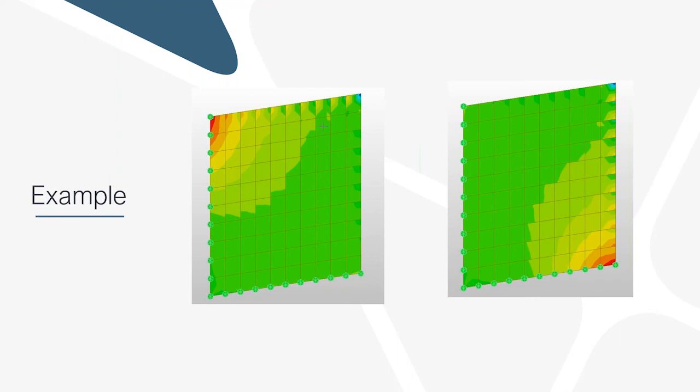So if the structure's steel, it's not as susceptible to the same type of cracking that concrete is, but its properties are such that if it does crack, it's a much bigger issue than if concrete cracks. If concrete cracks, the steel can just carry the load, help redistribute the load to other areas, and you haven't necessarily compromised your structure in any kind of way. But steel is a whole different animal if you develop cracks, which is why in steel avoiding high stress concentrations is extremely important. Granted, we want to do that always, but it's not the same issue, depending on the scenario. So it's good to just have an understanding of how boundary conditions can affect these things and how they change in real time with respect to real world application.